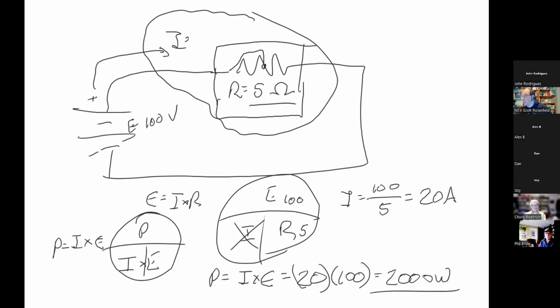Well, on top of that, we just took that resistor and we actually shorted out half of it. So maybe it's not even good for 1200 watts anymore. So what's going to happen to that resistor? Let's say it's only now rated for 1000 watts. And we're now putting 2000 watts of power through it. What's going to happen? Same thing as what happened before. It would heat up and it would probably catch fire, potentially burning your house down. Or exploding. Hopefully not.